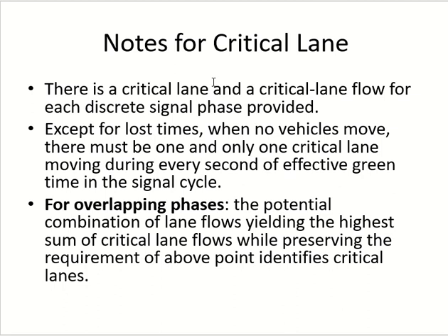Then from the total time, if you subtract the lost time, in the remaining time, whatever remaining time you have for the signal, in that time at least one critical lane should always be open. Okay? So outside the lost time, at least one critical lane is always open. Okay? Clear? Outside the lost time, at least one critical lane should be having yellow or green.